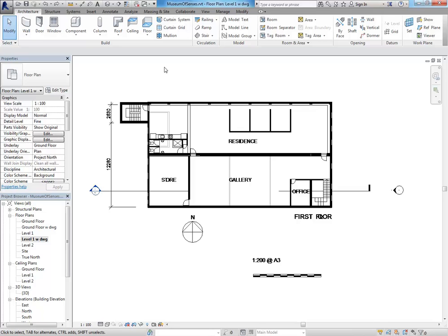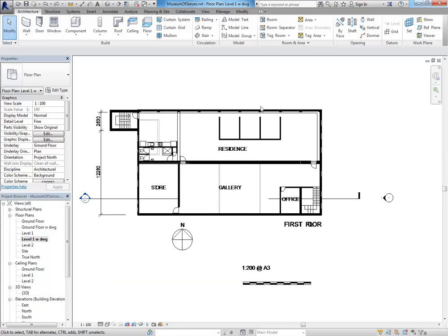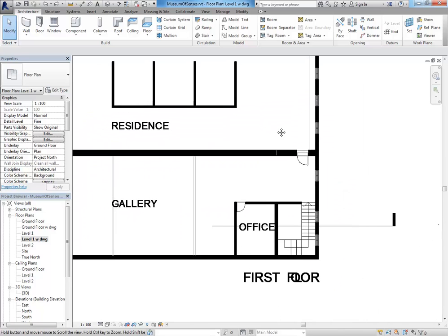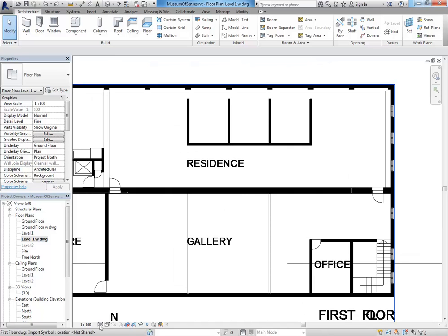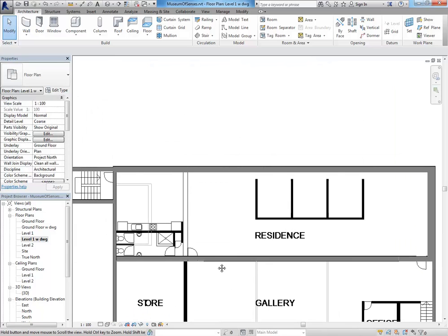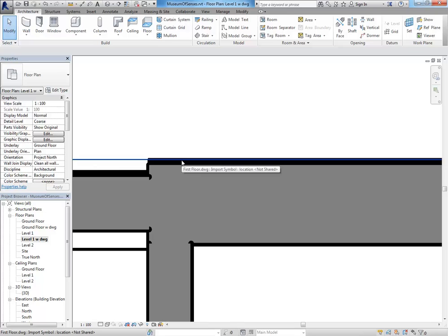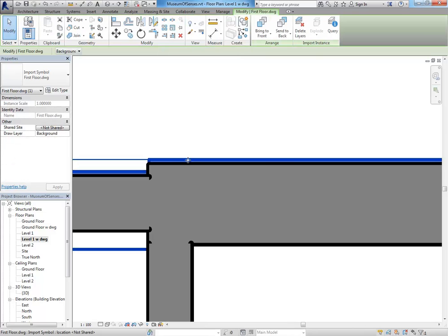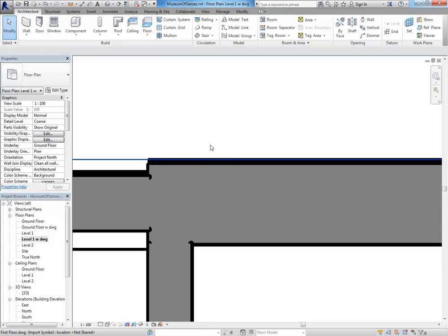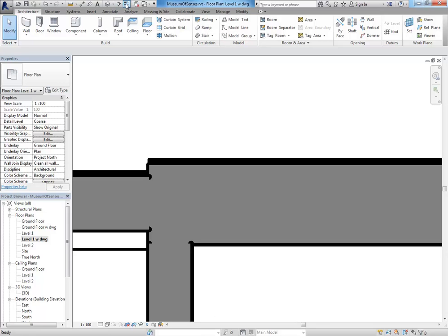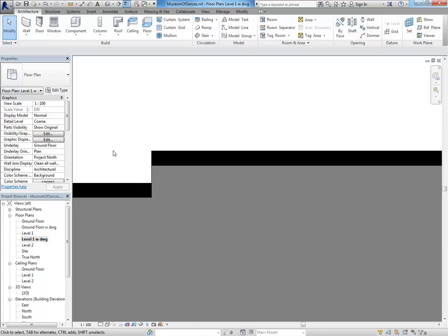Okay, so I've got the first floor walls starting to be set out and lining up with my ground floor walls. I just thought I'd show you quickly the floor plan there. I've left it the way I had it before, in other words, not properly lined up, and you can tell when I'm in this course display that the drawing file is just slightly out of alignment with my walls. If you aren't sure and you want to get a better look at that, try thin lines, which hides your line weights so that you can see things more clearly, and that can help sometimes.